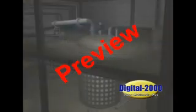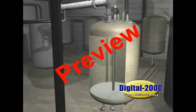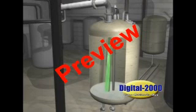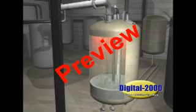Shortly before the accident, Synthron received an order for an acrylic product that was 12% larger than the standard batch size. Rather than fulfilling the order by making 2 smaller batches, managers decided to make a single, larger batch and to add all of the extra acrylic monomer during the first step of the process. But this was a critical mistake.